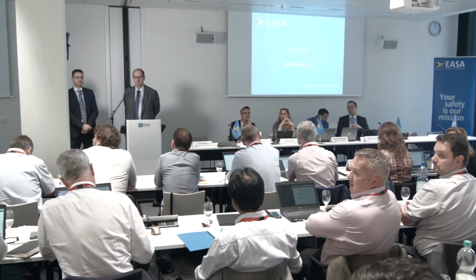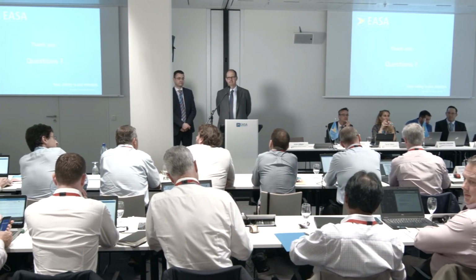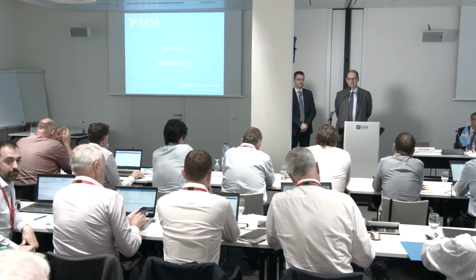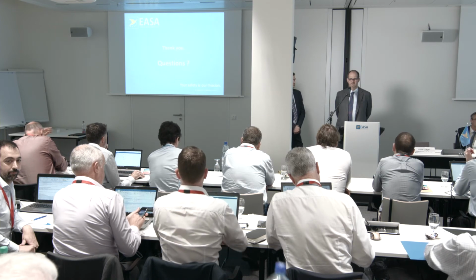I'm getting much more involved in Part M. And when we're doing our surveys and audits of Part M organisations and ACAMs, we're finding that there is quite a bit of confusion within the Part M organisations as to whether or not FAA-approved changes are acceptable to EASA or not, because they are not familiar with Part 21. They're not familiar with the FAA EASA TIP Rev 6. So it's causing some confusion, and we're finding that some aircraft are being presented for ARC renewals or C of A with FAA STCs on them or changes out of the TC holder that should have been EASA approved.